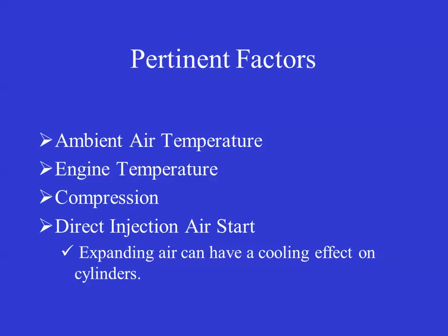Diesels are compression ignition engines. So if the air temperature in the combustion chamber is low, it may not be enough heat, high enough temperature to get it to explode, to get it to start to burn. This also includes the temperature of the engine at cold temperatures will also affect that.